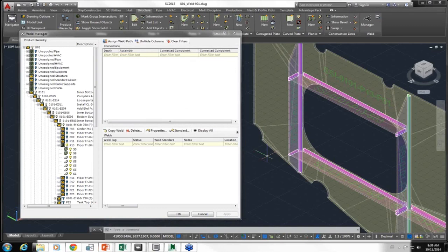So if I'm going in and checking the drawing, I know roughly what I'm looking at. I know this is a panel, and I know I've got a bunch of stiffeners on that panel, so I know what kind of weld to expect in most cases for this panel. So I can see at a glance, well, there's something odd here. I don't understand why that would be there. Now, maybe there's a good reason for it, maybe not.